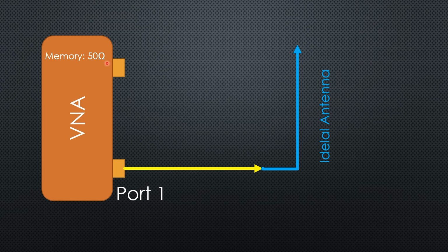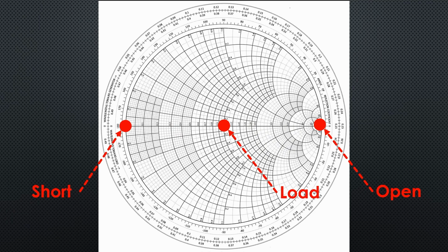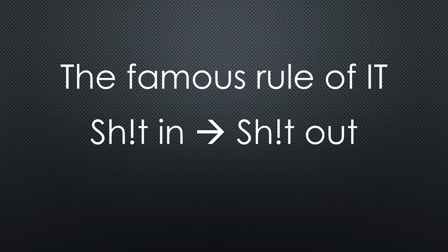So far, so good. But do we need to have a ton of resistors, capacitors and inductances to calibrate the instrument on all points of the Smith chart? Fortunately not. We only need 3. An open, a short and a 50 ohm load. If we calibrate even a cheap instrument at these 3 points, it will display all other points with acceptable precision. But do not forget, if we omit this calibration, these cheap instruments can show very wrong measurements. Also the professional ones, by the way.